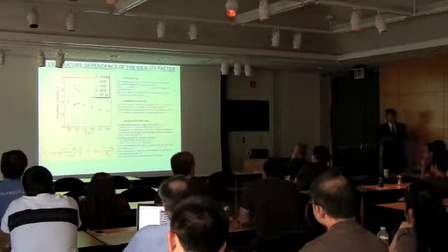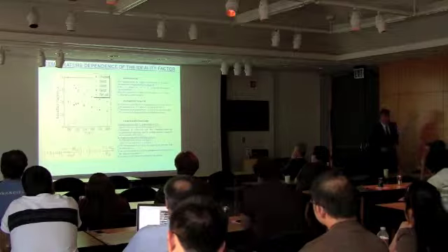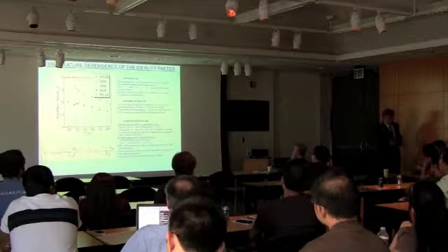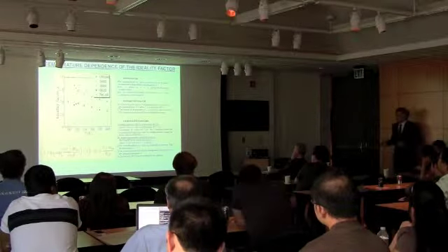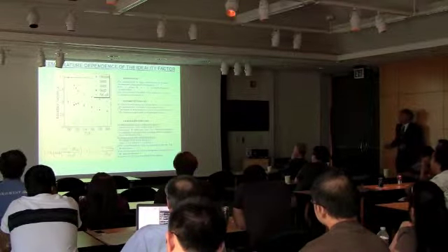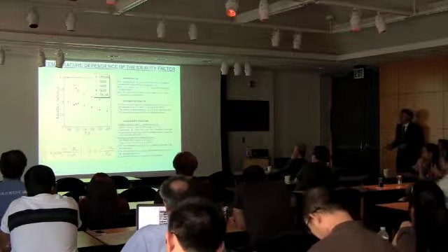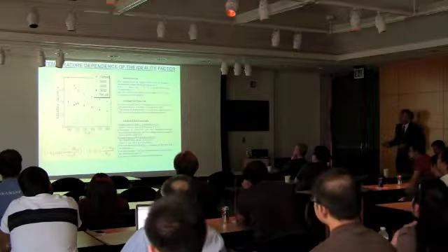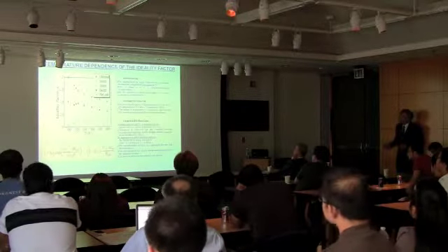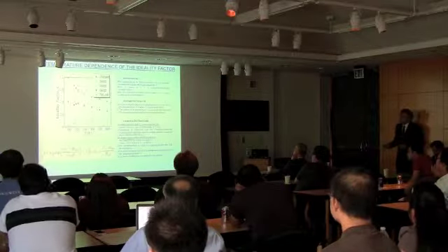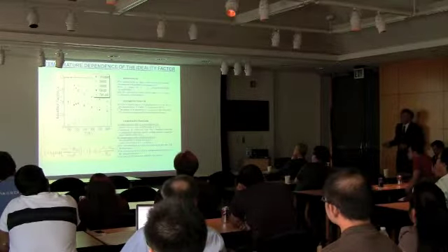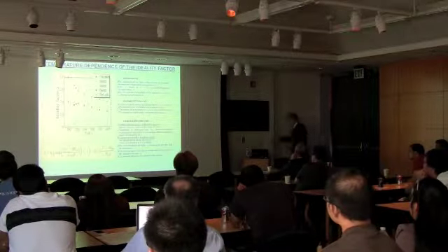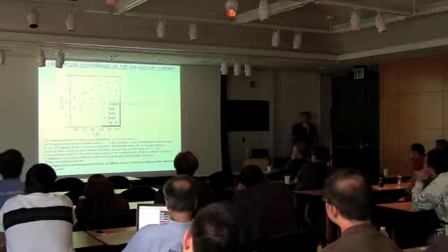And what is going on? Now recombination goes through the dots. So your PN junction becomes not as good. The rectifying characteristic of the PN junction is worse. When we start to dope, then you see that we have, first, a substantial drop with 2 electrons, 3 electrons. With 6 electrons, we have already a little bit worse, but better than undoped. So we still need to work on this to understand a little bit more and improve. And the same with the reverse current.